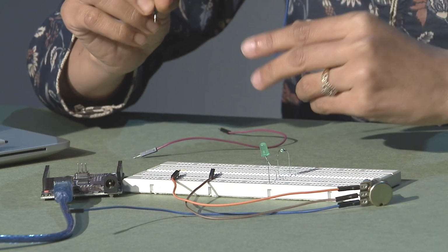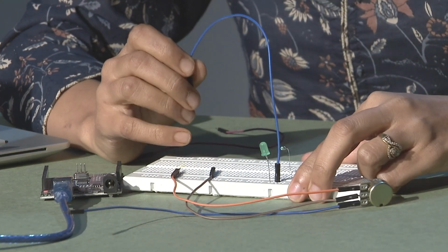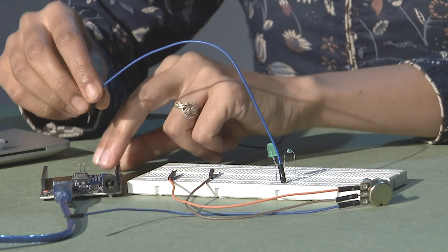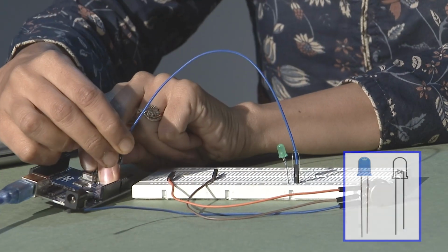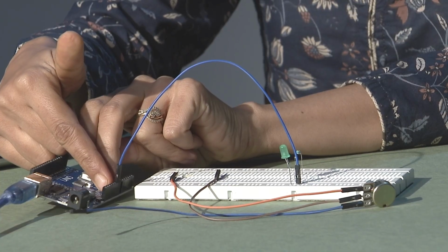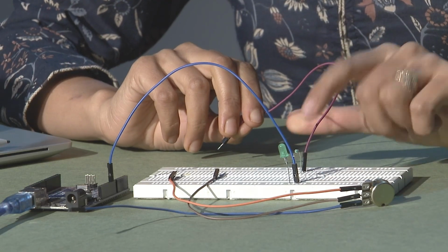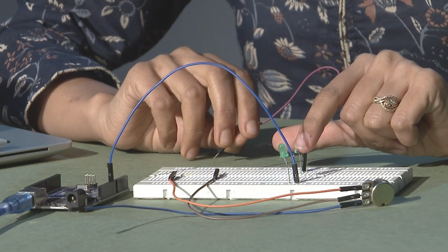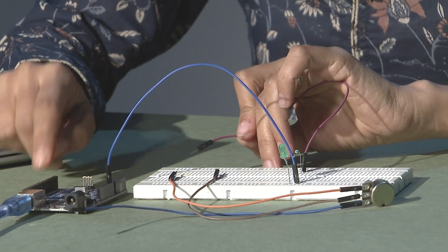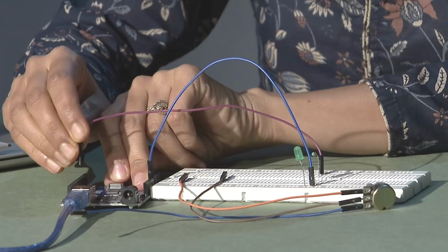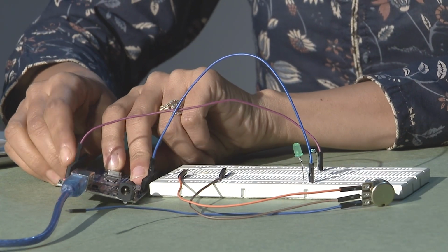Now, one terminal of this LED I will be using for the ground, that definitely will be your cathode terminal. So, always check the flag of your LED for this connection. So, here I am inserting this particular terminal into the ground terminal of my Arduino board. Similarly, we have the other anode terminal of the LED in sequence with the resistance, and that we can use on any of the digital pins in this port. So, let me choose one random pin. For example, we have pin number 10 over here. So, I have connected it.